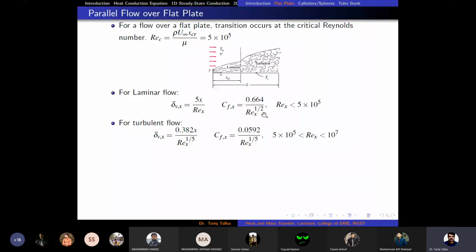That can only be done analytically by using the Blasius solution, which is a similarity solution only for laminar flow, because in that case we can simplify the Navier-Stokes equation quite easily. But for turbulent flow, there is no such simplification, because there are turbulent fluctuations. So we cannot reduce the equation to an ordinary differential equation, and the Blasius solution cannot be applicable.